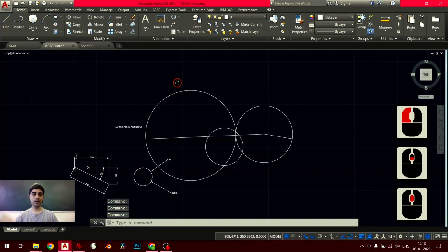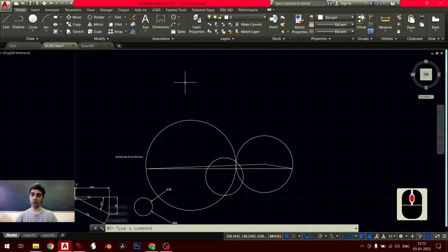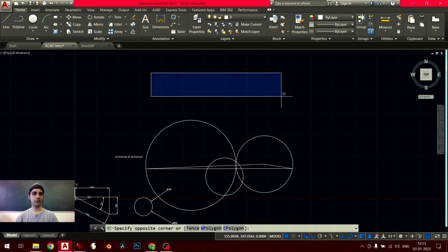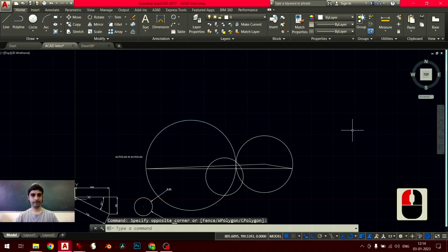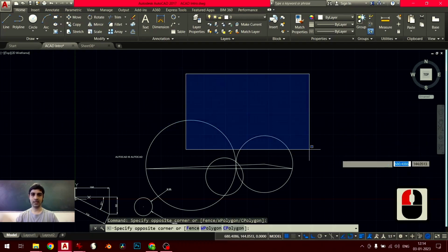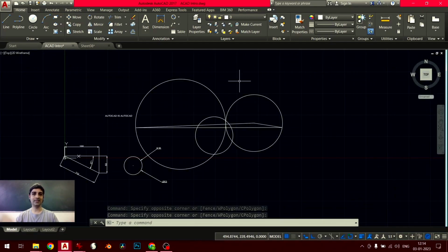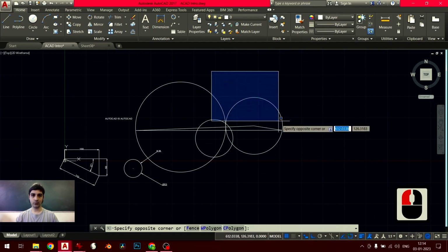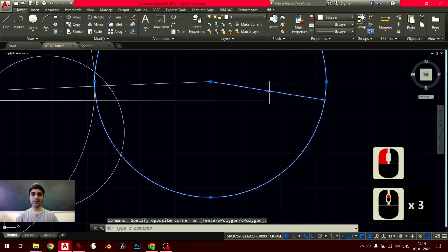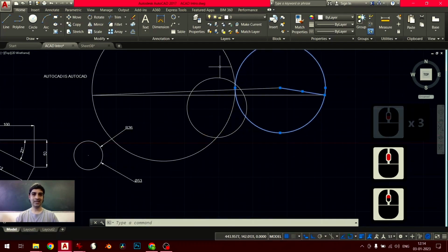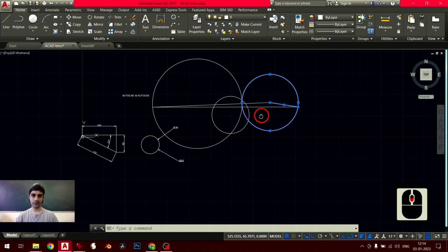The first one is called a blue box because it is a blue box. The way it works is you click your left mouse button somewhere in empty space. You click and release, don't click and hold. And then you move your mouse, you drag out this blue box, and then you click again. All right, one more time, click, release, and click. This box is going to select whatever's completely inside its borders. So if I do that around this circle, you'll notice it selected this line as well because it was completely contained inside it. But it didn't select anything else that cut its corners or borders.